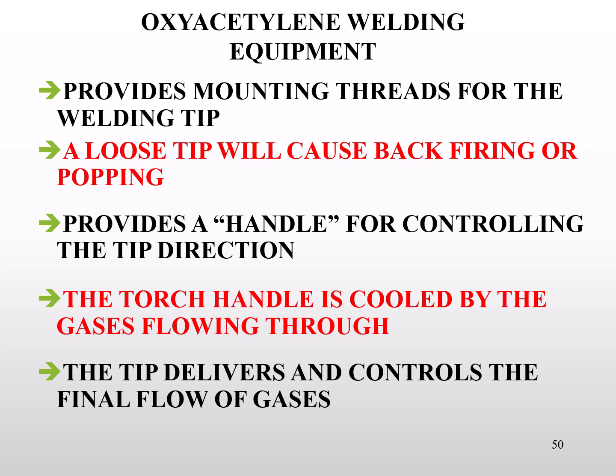The green hose will always be your oxygen, the maroon hose will always be your fuel gas, and the torch handle itself is cooled because the gases flowing from the valves are mixed within that torch body, providing something cool to hold on to while at the same time mixing the gases internally to get a much more even burn. The tip is there just to deliver the mixed gases to create the temperature.